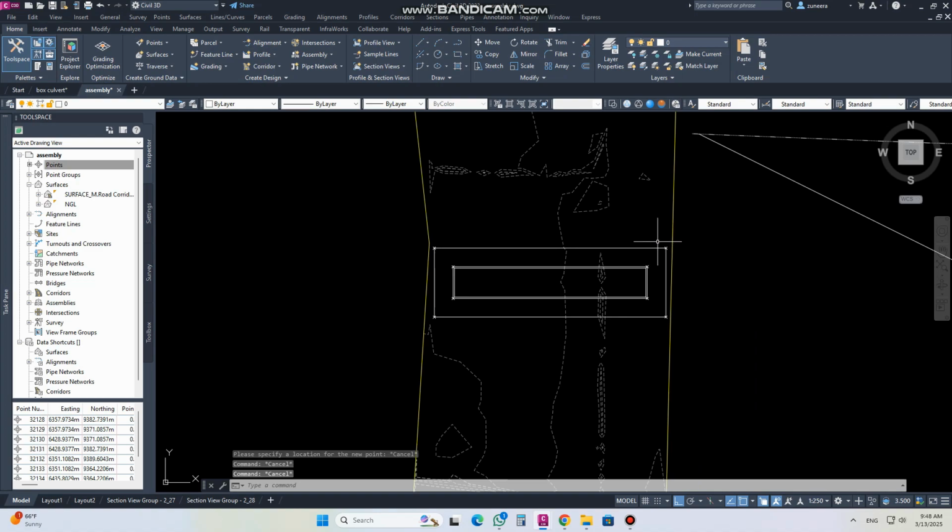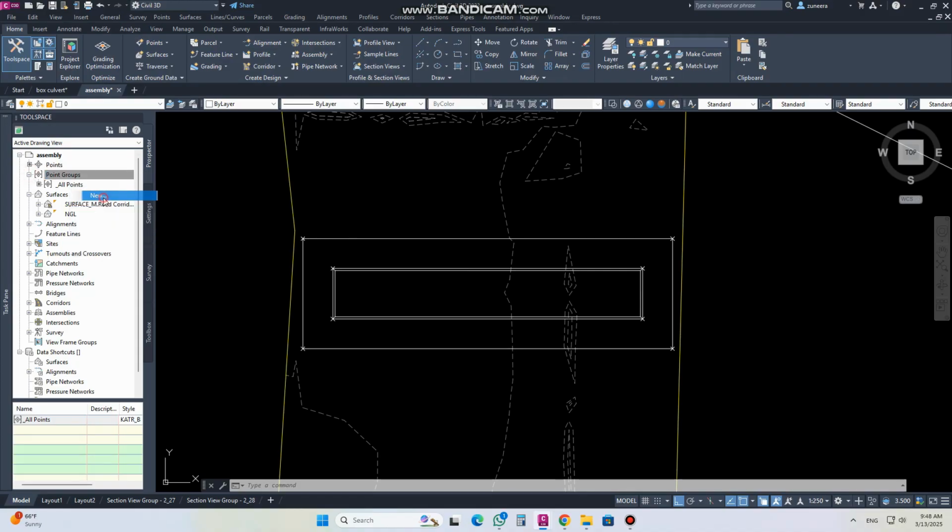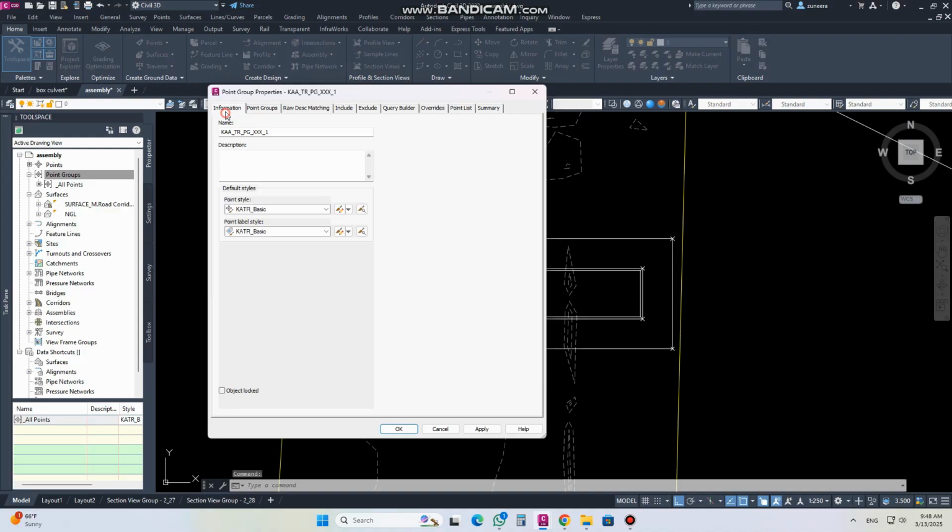Like this will be the excavation points, but if the surveyor does not bring them, you can draw your drawing exactly on scale, and then you can also calculate the excavation quantity. But mostly the surveyor brings them from the site. They check with the consultant surveyor, and then they bring them to us, and we can compute the volume from this surface.